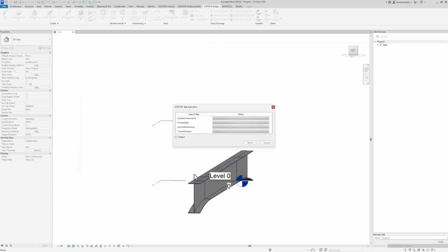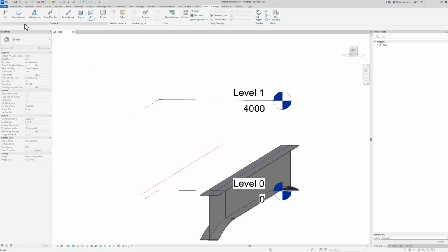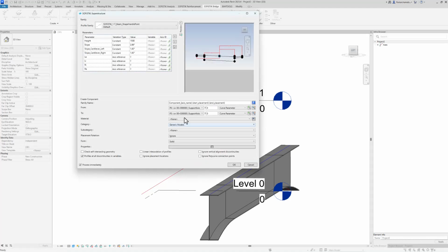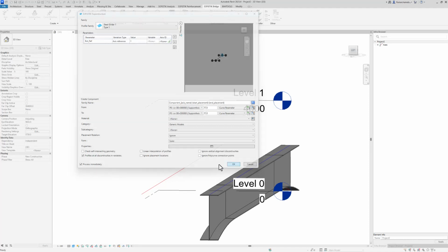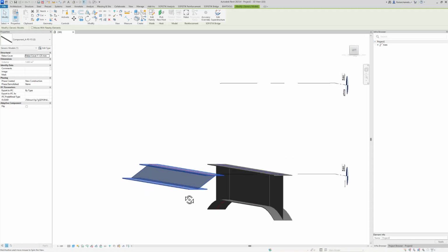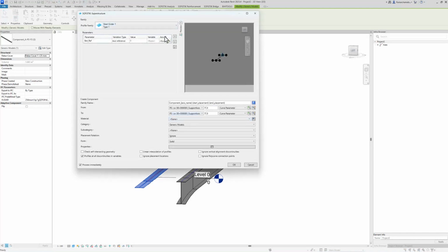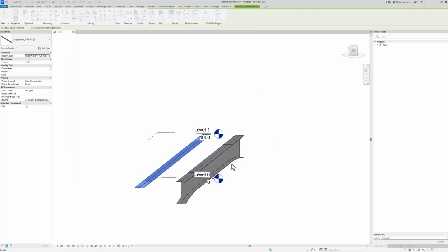And the program creates another secondary axis with the horizontal offset that follows the main axis. I can now use the already existing superstructure family and base it with its adaptive point on the secondary axis. You can see once more the original geometry. And just for a showcase, I now want to connect it to the vertical reference. Let's see what the program now creates for us.